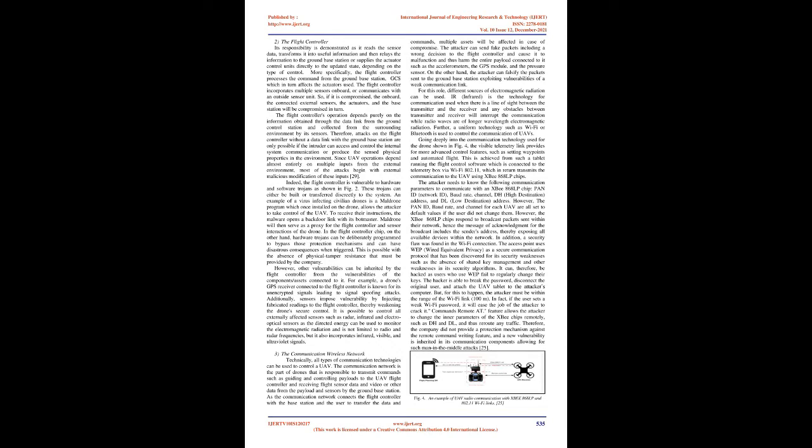On this basis, spoofing signals must be generated in such a way that they have similar characteristics to those of legitimate GPS signals, and the spoofing signals produced must be radiated to the UAV at the correct signal strength. A developer of the drone's internal signal processing algorithm can make the drone prone to spoofing attacks if no encryption is implemented for such a method. The company of civilian drones that use the civilian GPS system makes their produced drones prone to spoofing attacks if they don't implement an encryption algorithm or cryptographic techniques to encrypt its GPS signals.